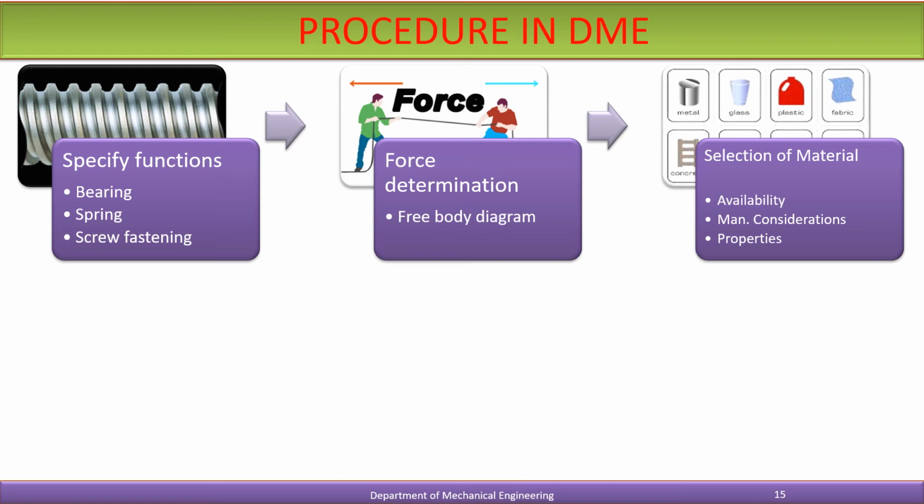These have complex shapes. These components are made of cast iron, because the casting process produces complicated shapes without involving any machining operations. So we need to design these fundamental factors: availability, cost, mechanical factors, and manufacturing considerations. We will select the material.